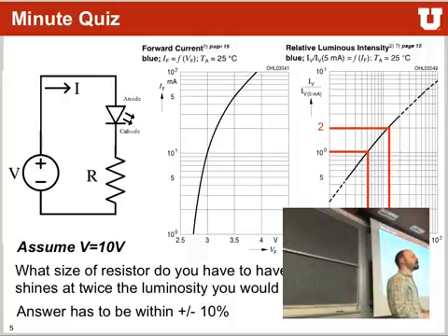Yes? I had a hard time finding out what the rail voltage was going to be on the board. Is that something that's predefined? Depends on what you hook up to it. If you hook 5 volts up, stuff will start smoking because your MSP is only rated up to 3.6 volts. Generally, the MSP will run anywhere from about 2.1 volts up to 3.6 volts. So it really depends on what you provide to the whole board itself, since we don't have a regulator on the board. Most of the time, it's like 3 or 3.3 volts, but it's up to you to decide.